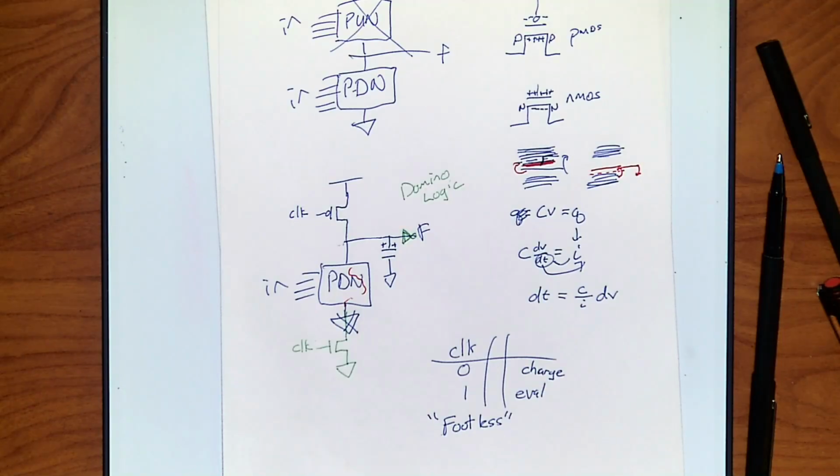In dynamic logic, you just recognize, oh, it got this kind of problem, right? And therefore, I just add the buffer and you get basic domino logic. And then everything after that is just efficiency tweaks. But you've basically got stupidly fast logic at this point. That can be cascaded plenty fine within a clock situation. So you can do whatever you need.